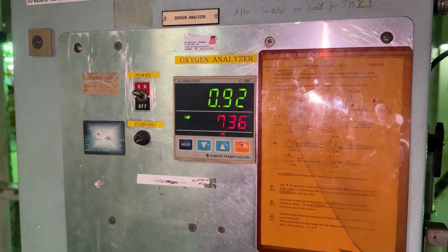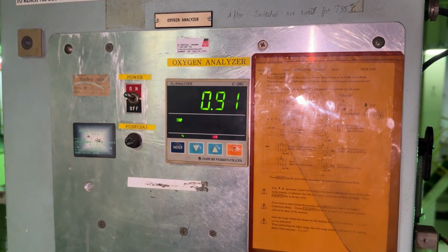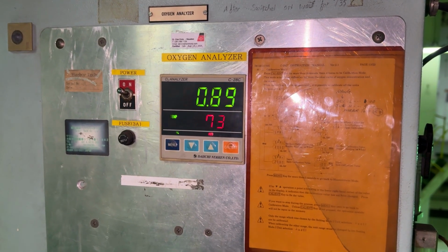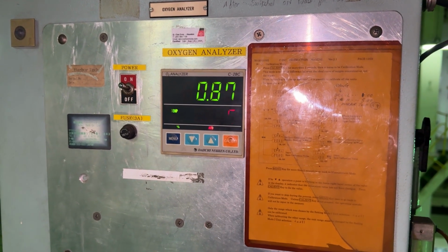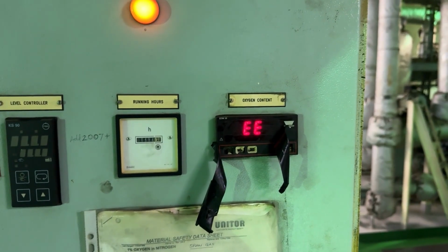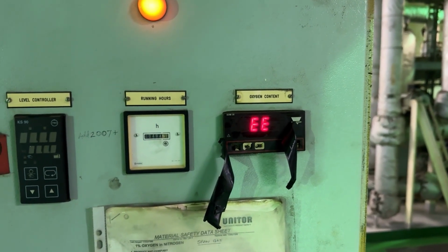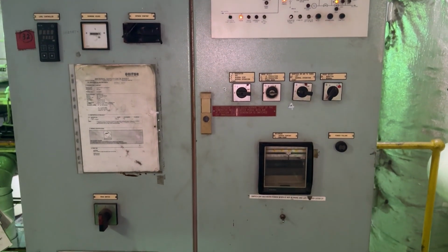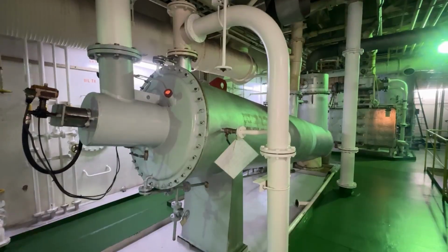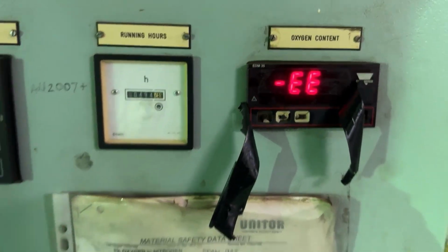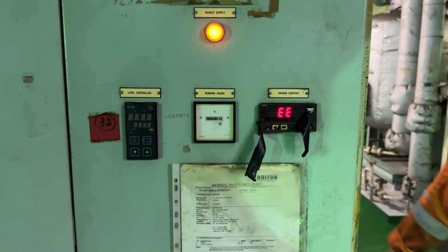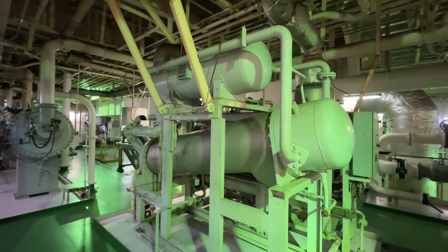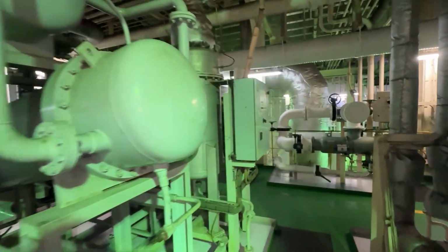And about the erratic reading of oxygen in the IG panel, our oxygen is showing correctly in the oxygen analyzer meter. This oxygen analyzer gives feedback to the oxygen meter installed in the IG panel. That means this display installed in the IG panel is not working, and we will raise a requisition for the display also. So that's it guys for this video. I hope you understand the concept of the IG plant. And as we don't have spares for the water level controller and oxygen meter in the IG panel, we'll make a requisition for the new ones. So for the next video I will be explaining the IG chiller plant in detail.